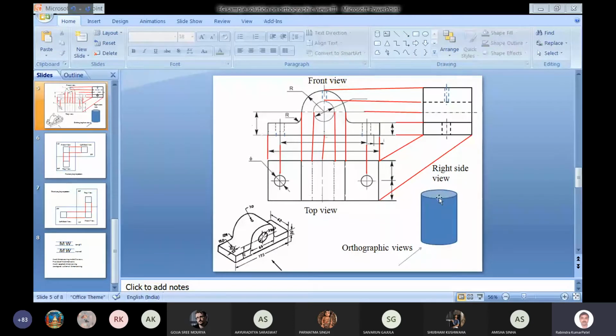We will just draw two boundaries of the cylinder, and corresponding to the top face and bottom face we will draw two lines. So we will get a rectangle if it is a complete cylinder. If it is a semi cylinder, we still get two boundaries at this point and this point. So corresponding to that we have drawn two continuous lines.